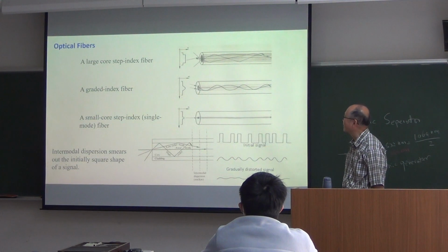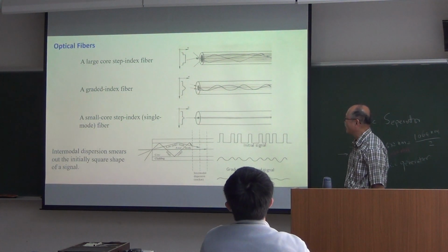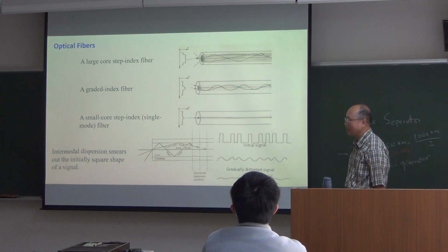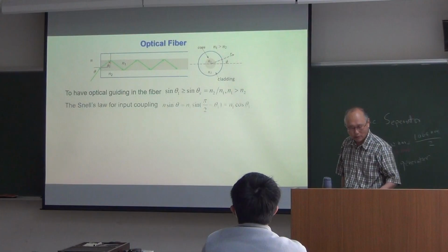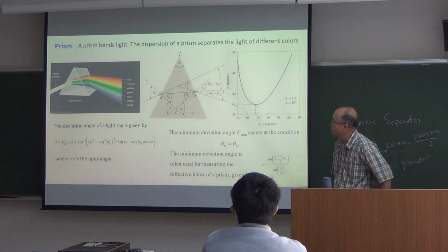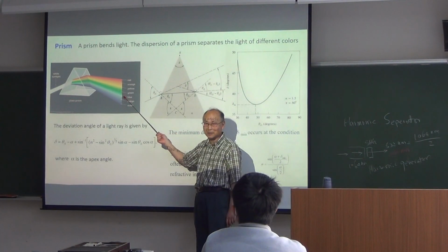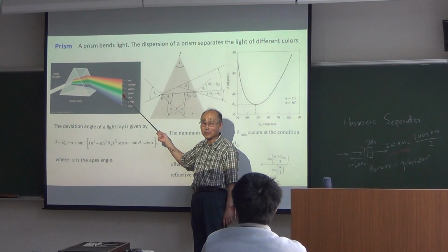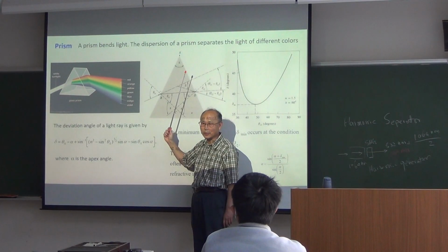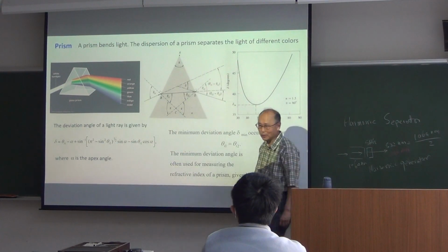Not quite the chromatic dispersion. So now we touched upon some concepts of different kinds of dispersion. One dispersion is this: you already understood, this is material dispersion, because the dipole will oscillate with different strengths at different frequencies. So we have material dispersion.